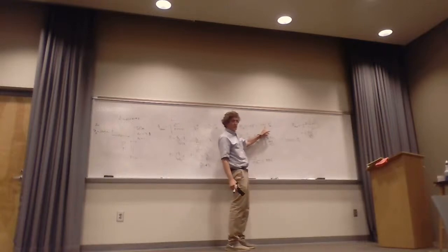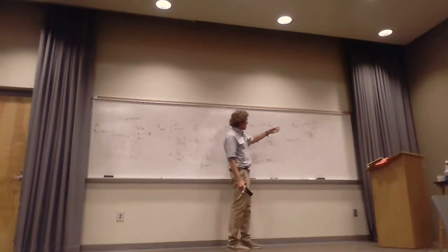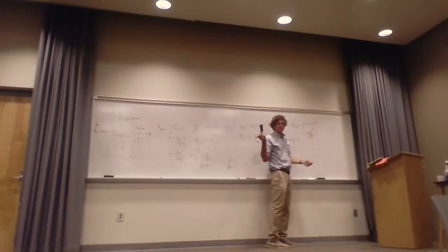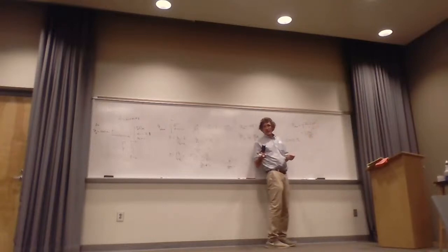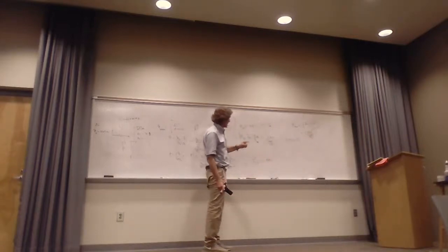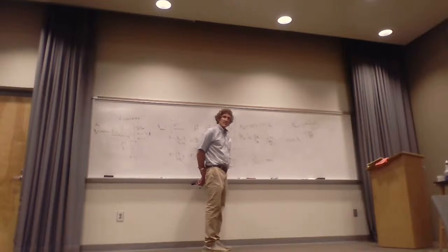This is one way to get it. You follow me on this, class? You can just take the E field and square it, because if you take 1/2 the real part of E cross H, H is E over eta, so you're going to get an E naught squared no matter what you do. The E field in the Teflon is 0.82. So you take 0.82 squared, divide it by 2, then divide it by 120 pi, and multiply by the square root of 2.1. What do you get for that? I think I provided you with this answer, but I'm not sure.